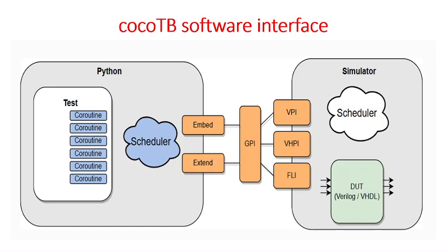We should be able to create this much amount of delay in the hardware. So many things are involved in this. There should be a communication between your CocoTB and your DUT, that is design under test. Now, design under test is mostly written with the help of Verilog or SystemVerilog. How this communication happens is based on the GPI, that is generic programming interface.